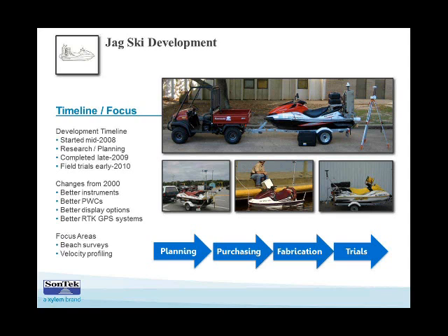And so now there's really no need anymore to do this monkey business with correcting to a local tide gauge after the fact and interpolating and still wondering if you actually got those values correct. If you've got the upgraded PCMs like we do now, then you've got a fixed and absolute vertical reference, and all you have to do after the survey is convert from ellipsoidal elevation to orthometric, which most software packages, most GIS programs can do, and you can always use NOAA's free VDatum tool, which is very good for transforming horizontal coordinates and vertical datums.